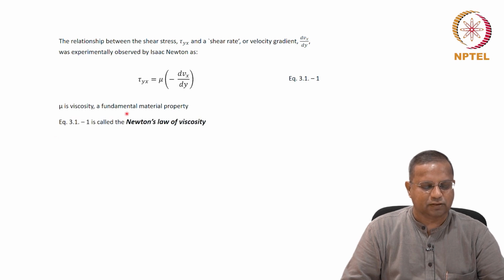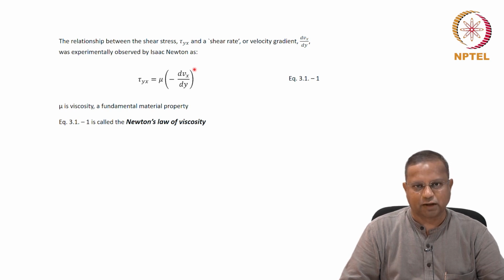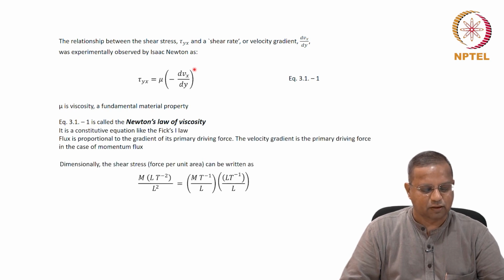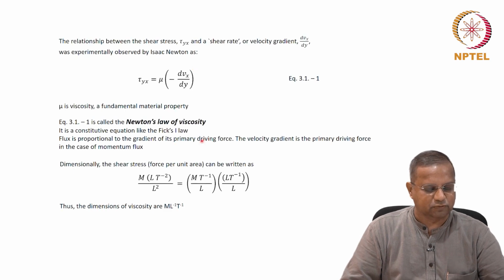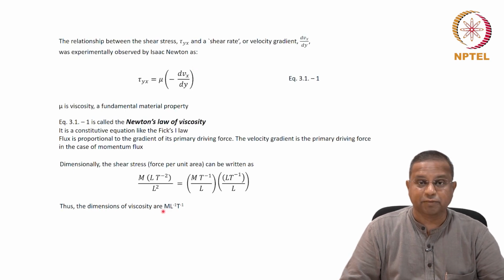And viscosity is a fundamental material property. Also, Newton's law of viscosity is a constitutive equation similar to Fick's first law in mass flux. Also we saw the units of viscosity; the dimensions of viscosity are M L^-1 T^-1. I showed you a way to work out such things from known relationships when you know the dimensions of the other quantities.